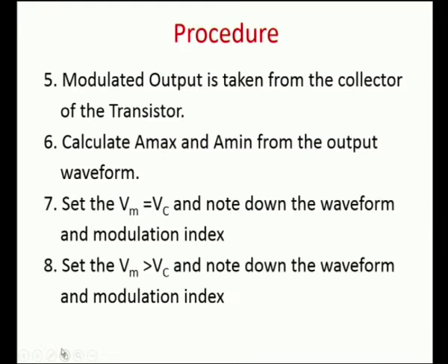Observe A max and A min from the output waveform. Compute the modulation index value mu. This is the first step. You can repeat it as many times as you want. And there are certain things that you need to see with respect to AM modulation.